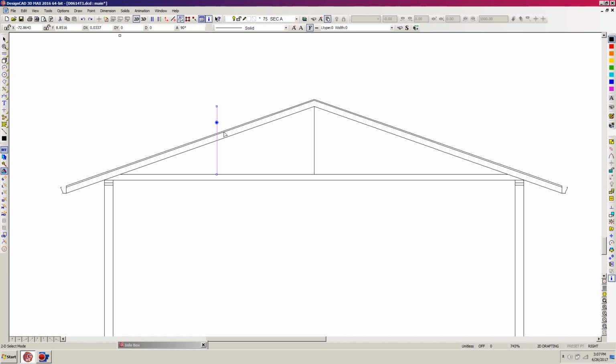And I'm going to select this line and use the line trim command, which is the underline command, and get down a little bit closer. Now I'm going to hit E again, and that time it worked. So I have my center line here, and I have my halfway line here, halfway between the center line and this point. And so now I'm going to draw another line that goes from here to here using V for vector. Right click to snap to that point, and then right click to snap to that point, and hit my scroll button to activate the line.